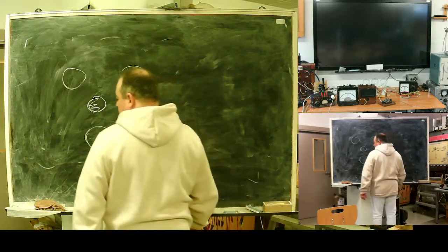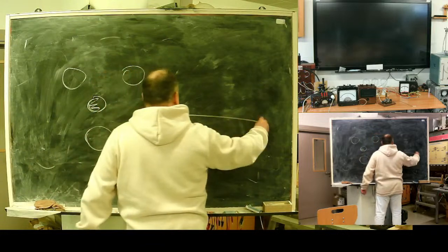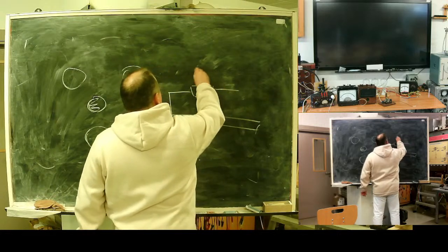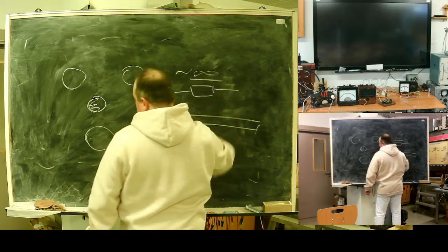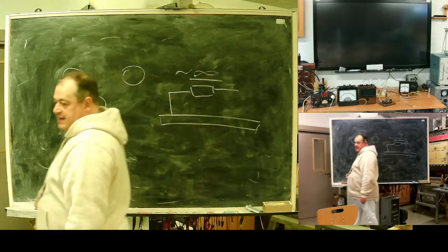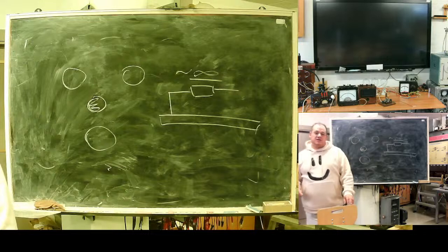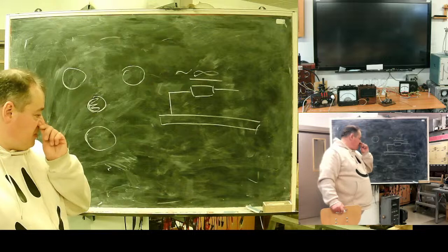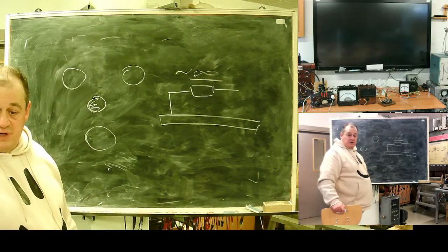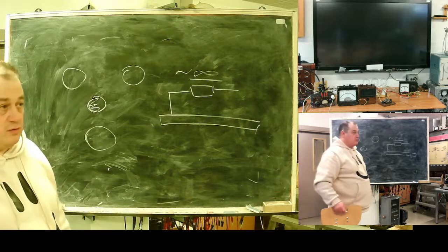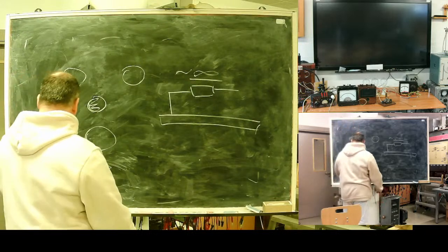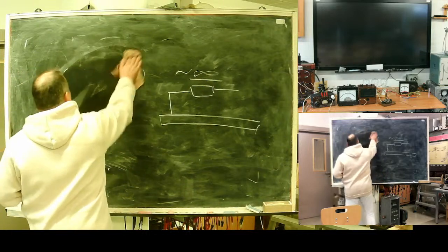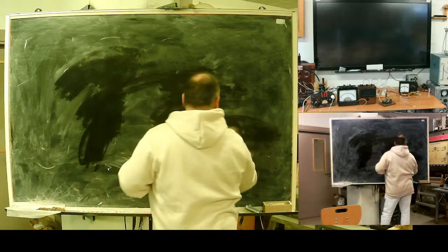For all such transformers, for zero sequence, we will have approximately infinite resistance. Very high zero sequence resistance, because zero sequence magnetic flux closes in the additional leg, and creates high reactive resistance, or low reactive conductivity.